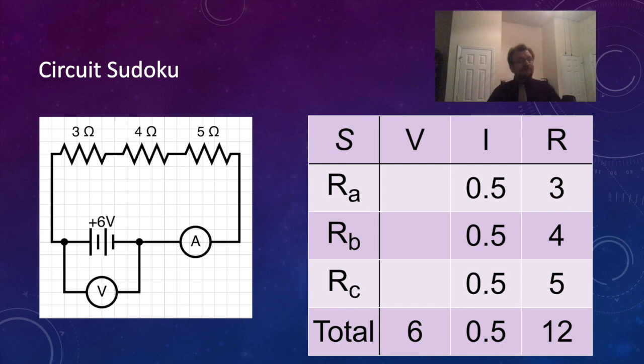Now from here, we've got Ohm's law, V equals IR. I have my current, I have my resistance. Now I can multiply the current and the resistance together, and that's going to give me the voltage. That's going to give me the potential difference across each resistor, so the voltage drop across each resistor. That's going to tell me the potential difference of the electron before it enters the resistor and right after it leaves the resistor. And that's what I can use to then calculate the power that each resistor is using as it goes around the system.